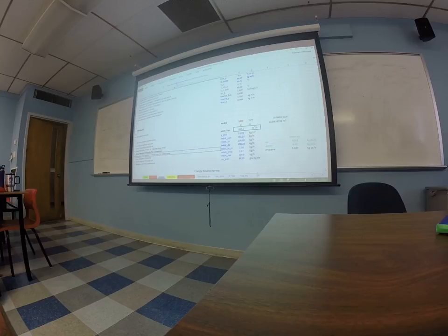That's the dry air, right? And here is the air that came into the chamber from the outside. So it would be how much air I'm actually sucking, and it includes the dry air and the moisture that came from the room to the combustion chamber, including the moisture that it sucked from the room. Great, thank you.